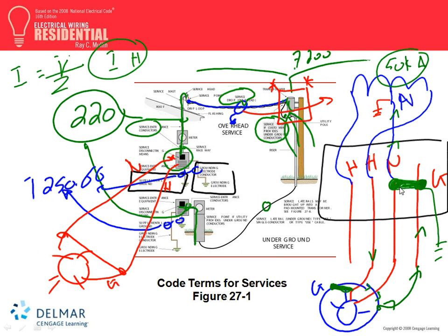They don't want to cut the whole city out of electricity because just a branch hit the transmission line. That's a whole different animal. They keep closing them, and if it keeps tripping a couple of times, then they isolate the system and send the crew to maintain it.